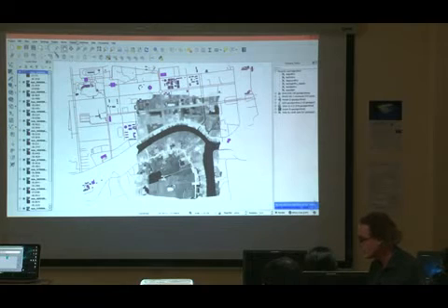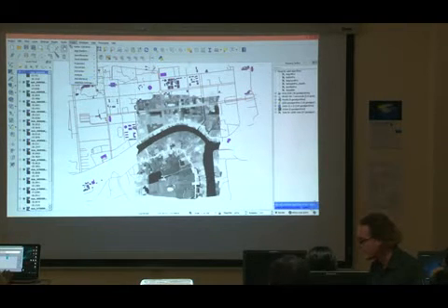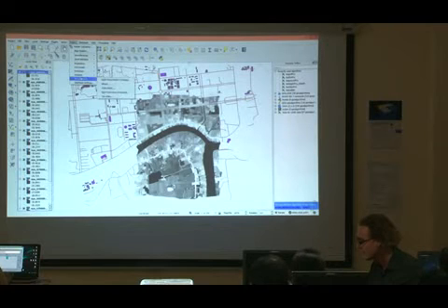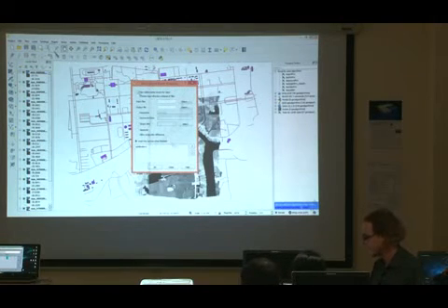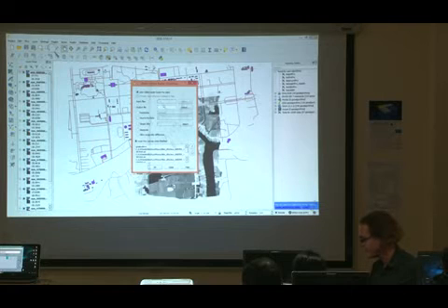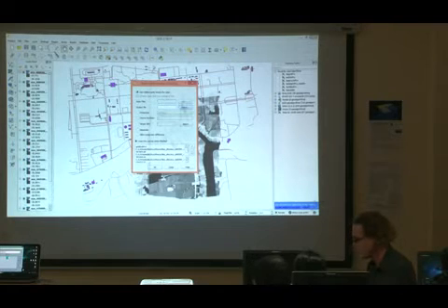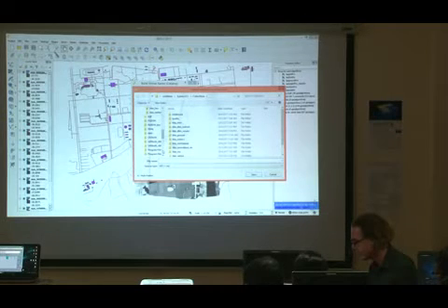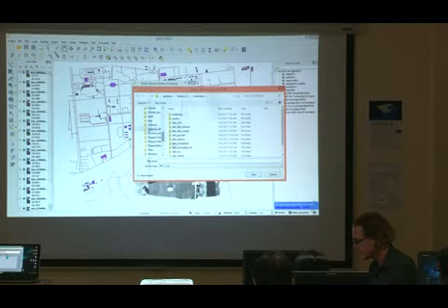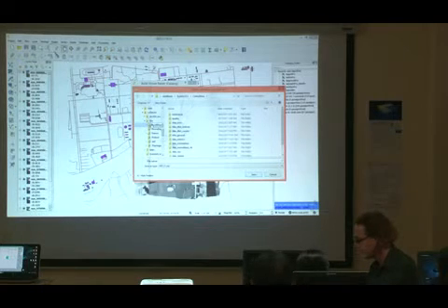And if you know QGIS, I can generate something called a virtual raster. Build a virtual raster. I use all the visible rasters. And I output a file called Ayutthaya DTM.